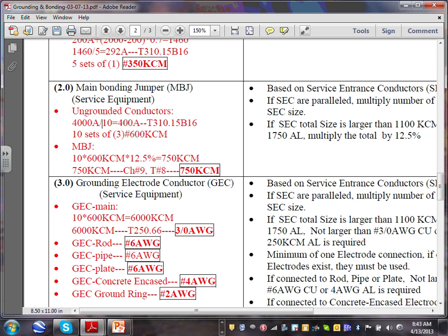The reason, guys, why it's too big is, how often do you have a conductor to bond the neutral to the ground in the switchgear? What do they have? They have the copper bar, the bonding bar. I just use this one as a demo. You would never see this one in real life, because typically they have a big copper or aluminum bar tying the two together. So you don't have to worry about this. But if you were to decide single-handedly to get rid of that bar and put in a conductor, this is what will help you. Then when you size the copper bar, that will be the manufacturer's UL. They have their own rules, but this will be a guide for sizing that copper bar if you have to. So, yeah, that's how they get around it, by having a copper bar tying them together.